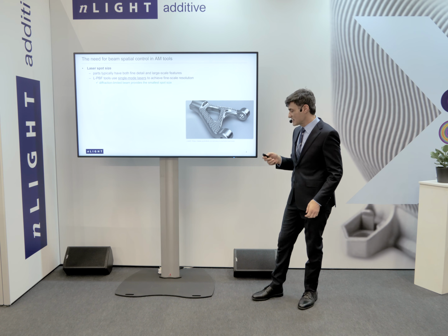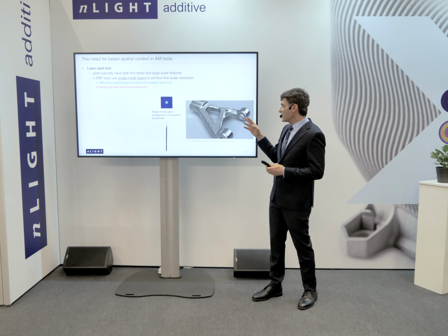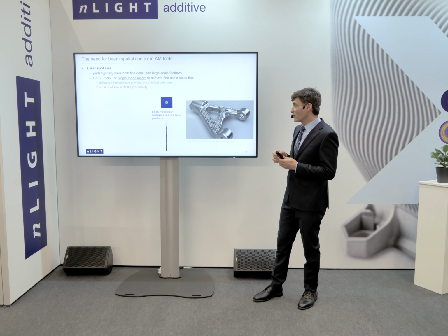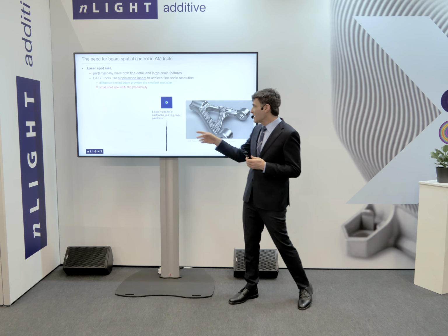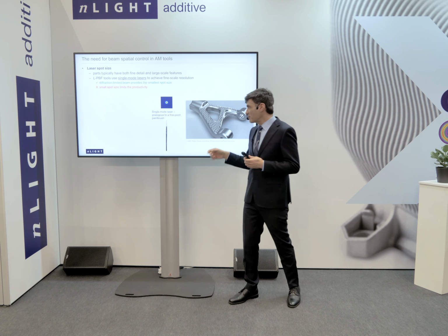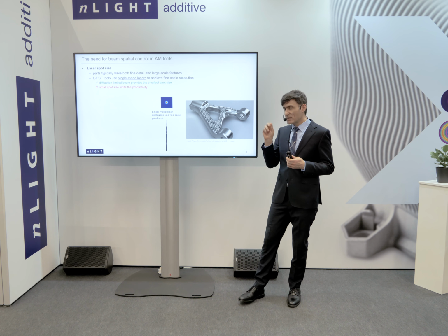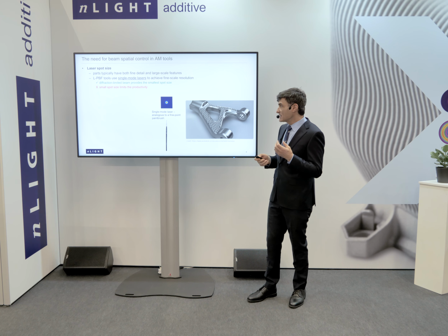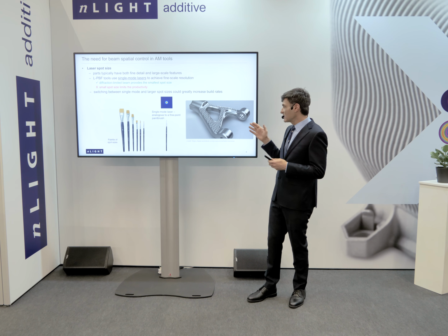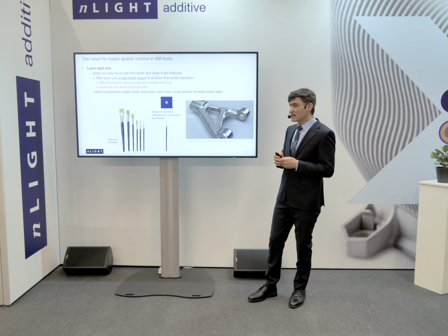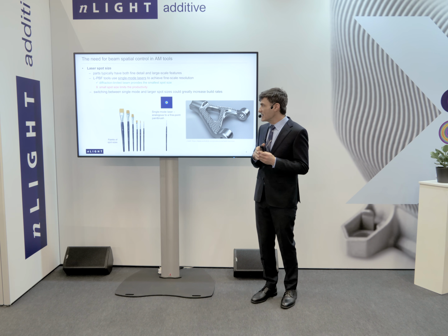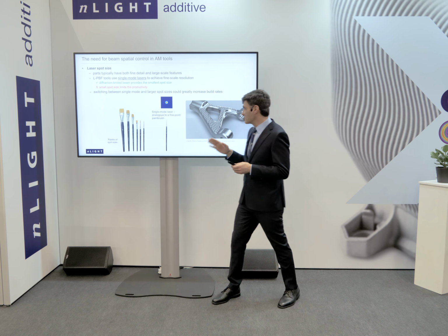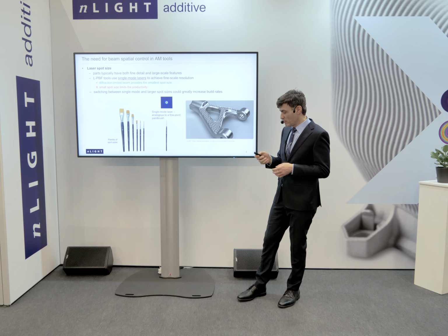these small features. However, when you go to write the larger features, the small beam doesn't work for you in terms of high productivity. The analogy would be if you had to paint a painting and only had a fine point paintbrush. To make these larger features, you'd like to increase the spot size and thus be able to increase the deposition rate. And in the general case, you need a laser that can go between the small single mode spot size and the larger spot size to maximize the productivity on the part.